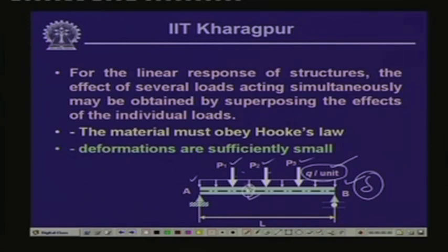And it is expected that the results which we get in either case should be identical. In the first case, we use the differential equation for elastic curve for the whole lot of loading and compute the deflection, and in the second, we employ the method of superposition by using the differential equation or area moment theorem, evaluate the deflection at that particular point for individual loading and sum them up.